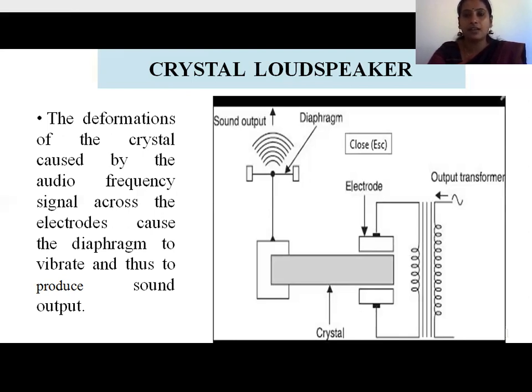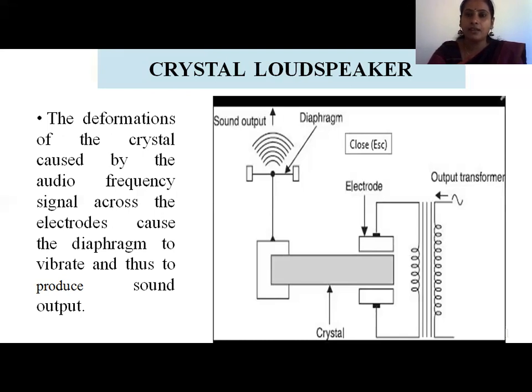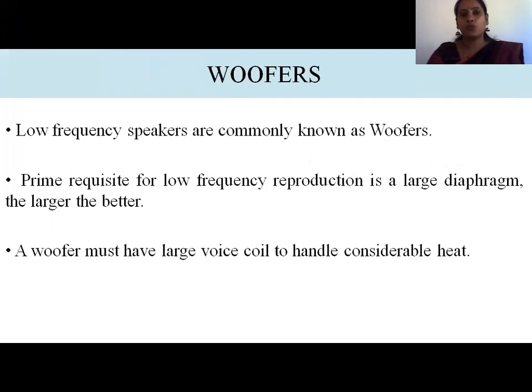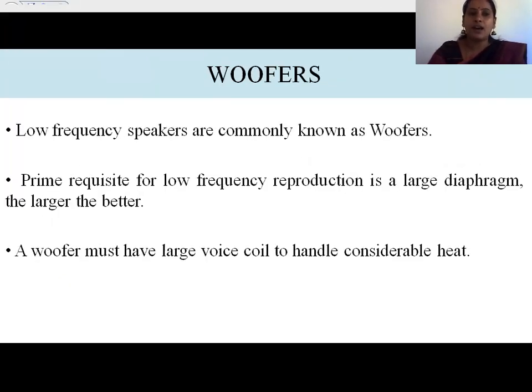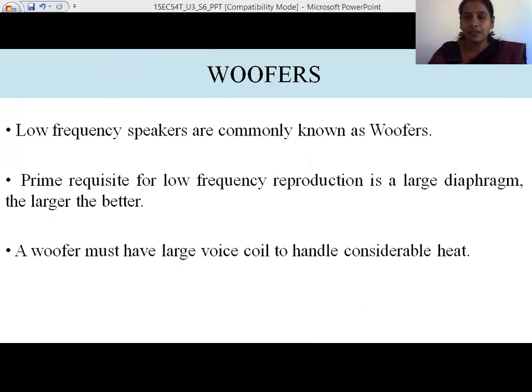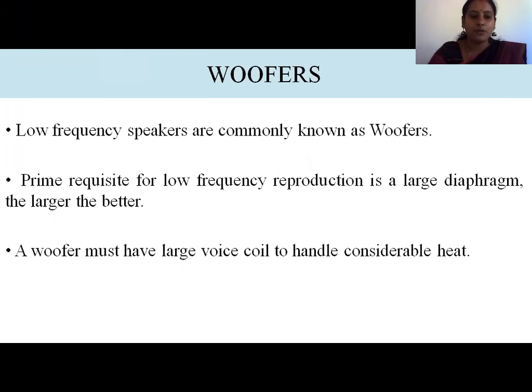So inside a large loudspeaker, it can contain many drivers. Okay. So this is about the crystal loudspeaker, where the piezoelectric effect is the principle of operation. So next we shall see woofers. These woofers are low frequency speakers. It is a specially designed loudspeaker that responds to low frequency signals. A standard woofer produces a frequency from 20 Hertz to 2000 Hertz.